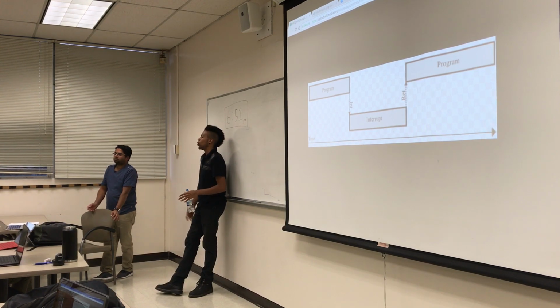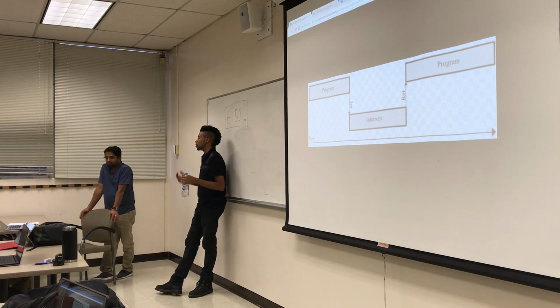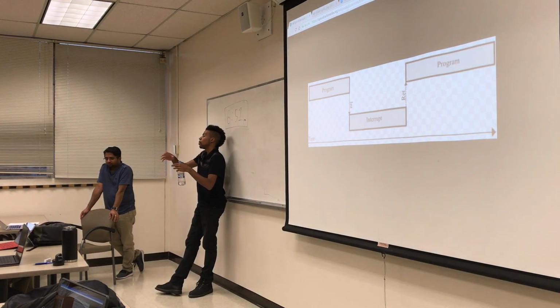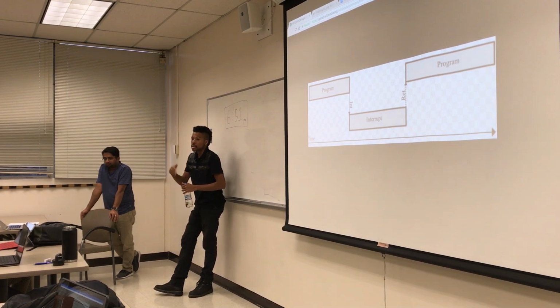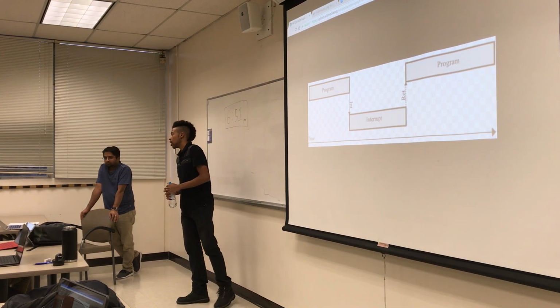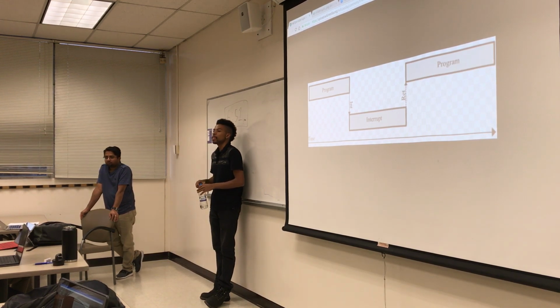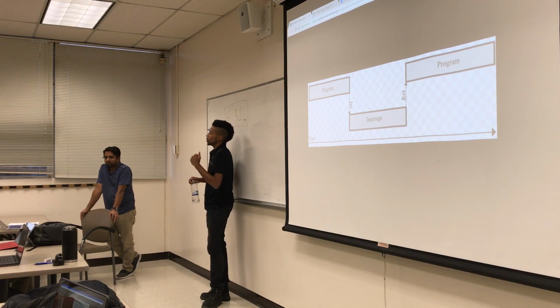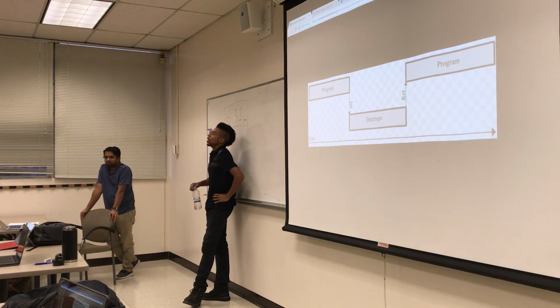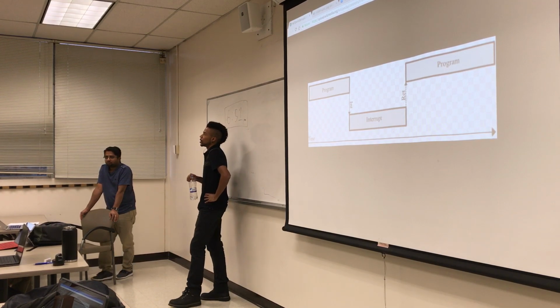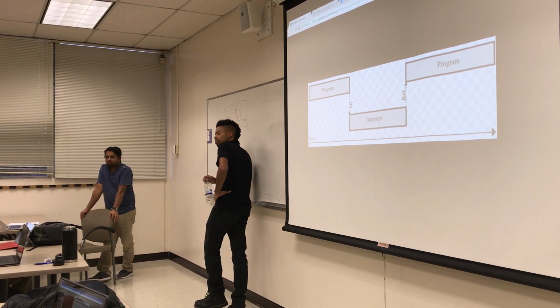So in that case, when you press the button, if it was set up sufficiently, you could have it trigger on a falling edge. Let's say before you press the button, it was high. Press the button, that level shifts low, and at that point you'd have a falling edge interrupt. You can set those up, and that's actually what your lab for that week is going to be about. You can also do it for rising edges. I haven't checked to see if you can do level. I'm pretty sure you can, but I'm not sure, because I've always done mine with falling and rising edges.